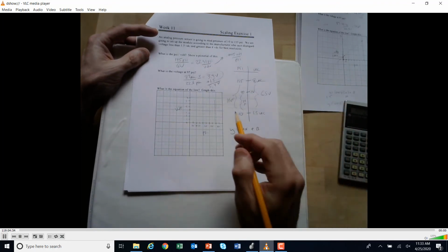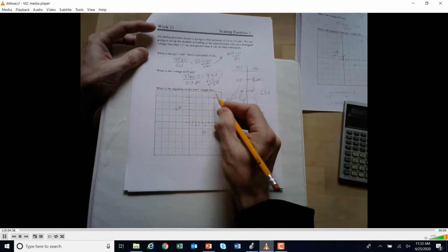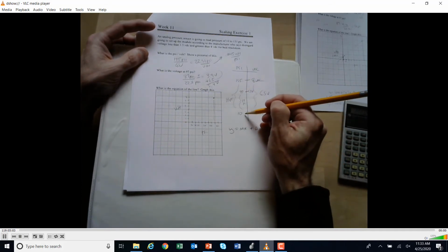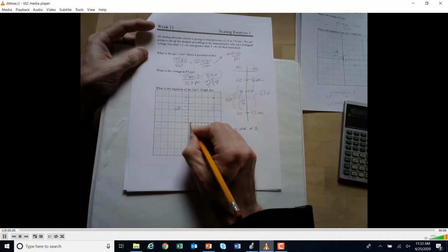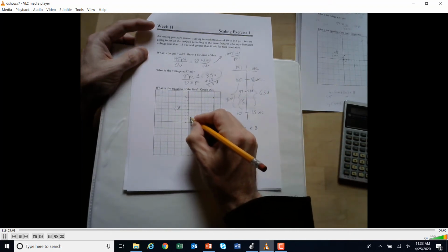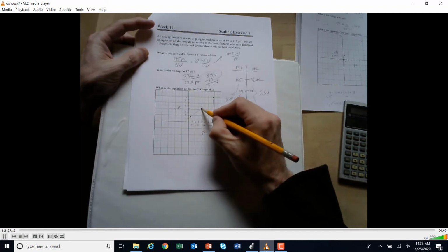And we would have 8 volts. So come across here. So there's my first point. That's this point here, x, y, okay? And at the other one, it was at 10 psi, which was here, kind of coming up. We were at 1.5 volts right here. So somehow there's a linear line that comes through here that we can get the equation of, okay?